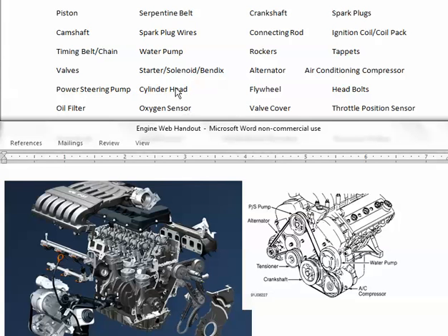And of course, it contains your camshaft as well. Your flywheel, as we spoke of already, is directly bolted onto the crankshaft. The crankshaft turns when we're running and transfers power to that flywheel so that we can get it to the transmission. We can talk about the flywheel being how the car actually starts, with the gears from the solenoid and starter bendix. Or we can simply say the flywheel takes the power from the pistons off the crankshaft, and due to its weight actually causes the power to be smooth because it has a large amount of momentum.